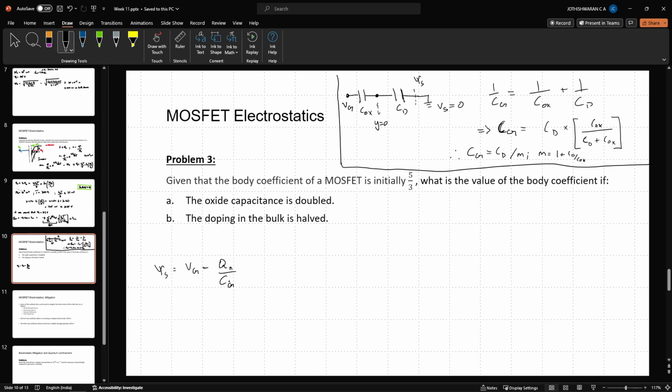which implies, essentially what this tells me is, inversion depends on this quantity here. So as Cg becomes smaller and smaller, I will need to apply a larger and larger gate voltage in order to switch my device from off to on. So that difference becomes significantly larger. Of course, there are some other effects here also, like substrate capacitance effects, but I'm not considering them. I'm only considering the depletion capacitance.